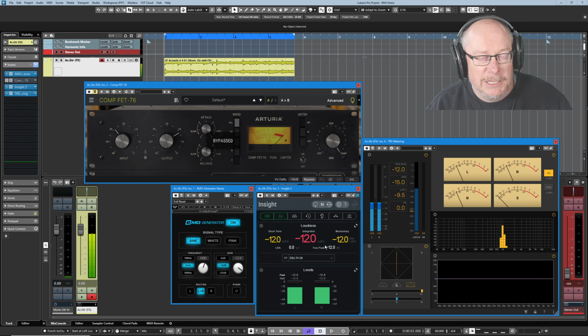But true peak is a very dangerous measurement to read because it's literally a single instantaneous moment in time. Generally speaking, when we're performing loudness comparisons, we operate over much bigger periods of time. And that in turn splits into K-weighted loudness, which is the thing that's dependent on our human ears, and the more scientific mathematical base of averaging called root mean square, where you basically take a bundle of values over a period of time, let's say a second, you add all of those values up together, and then you divide by the number of measurements that you've taken to get the general average.